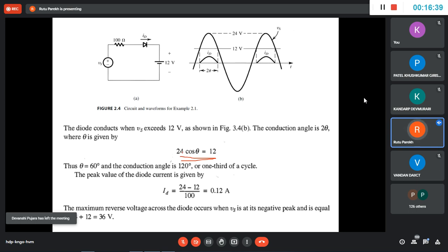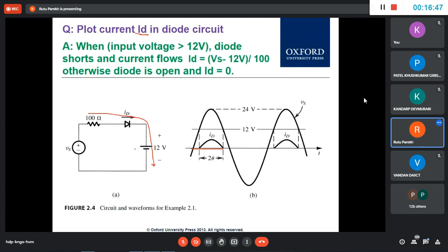Now this is your circuit, it is the same thing here, and the diode conducts when, sorry, this is 12 volt here. Don't forget this 12 volt. This is not shorted, there is a supply here. And this is the negative of the diode, and this is the positive of the diode. Now when this voltage is positive and more than this, 0.1, 0.2, then it will conduct. So it will only conduct for voltages exceeding 12 volt, from 12.1, 12.2, it is going to conduct.